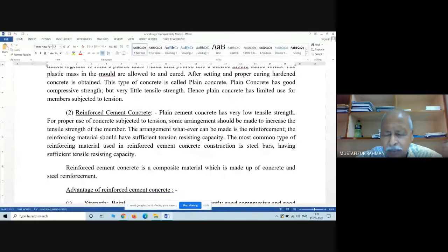If there is no connection between the beam and the column, then that beam is called a simply supported beam. This you know. Because of the load acting there, self weight as well as some external load, maximum bending moment will arise. If the load is acting uniformly throughout the span, then maximum bending moment will occur at the midspan, which is WL square by 8.